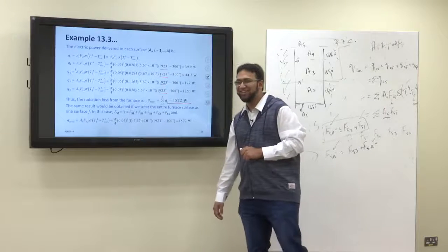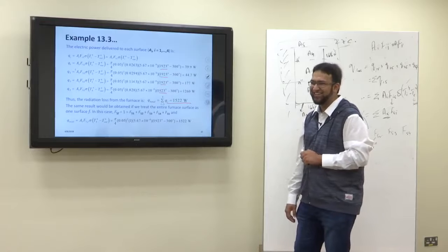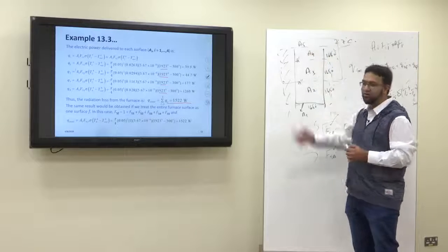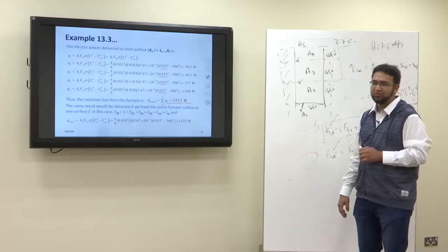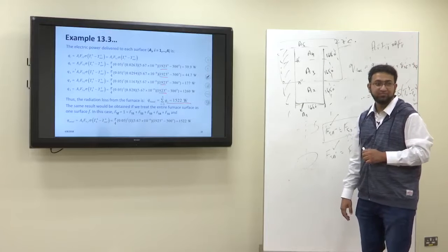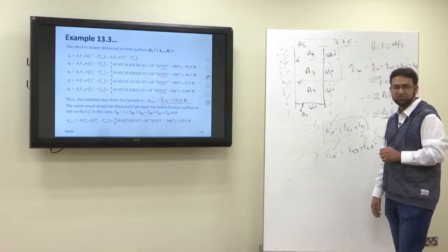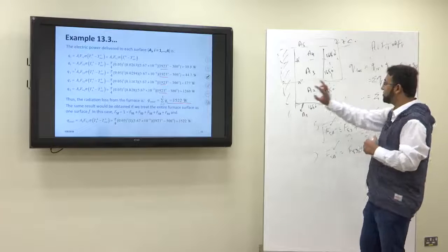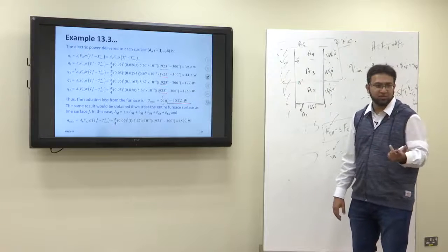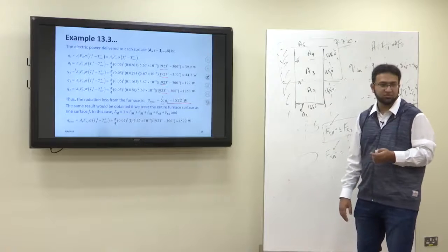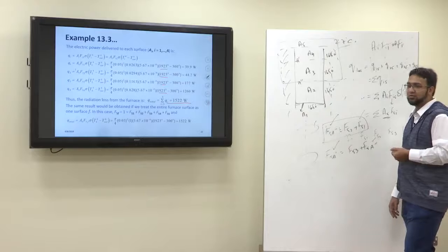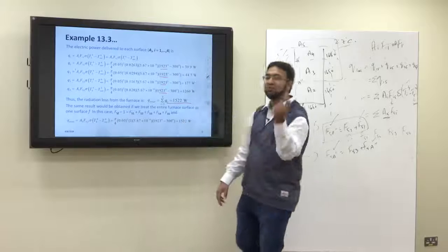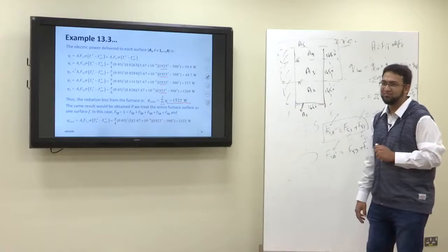Anyways, it's your turn right now. What you have to do is find out all the view factors from 5 to 1, 5 to 2, 5 to 3, 5 to 4, 5 to 5. You just start from 5. Just switch it. So 5 to 1, 5 to 2, 5 to 3, 5 to 4, 5 to 5, and then just switch the temperatures. All the areas would be the same. Everything will be the same. Then the Q will be negative? No, not negative, because then you will switch the temperatures. So it is the surrounding temperature to the power 4 minus the surface temperature to the power 4.